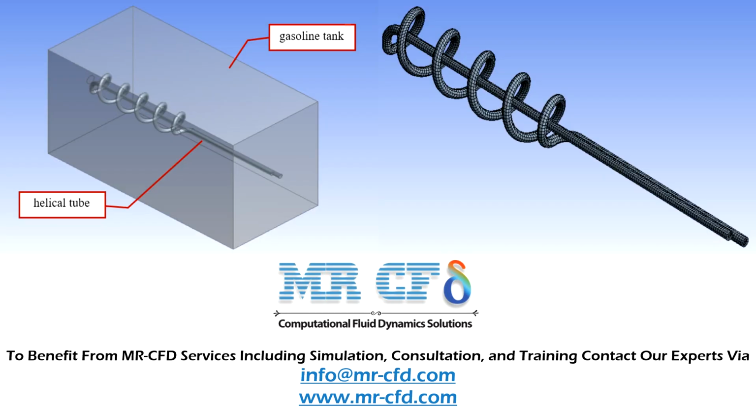We designed the three-dimensional geometry of the model using Design Modeler software. The model consists of two main parts, including a fuel tank and the spiral inner tube for hot water flow. To mesh the present model, we have used ANSYS meshing software, and the mesh type is unstructured. So the inner tube uses a finer grid.